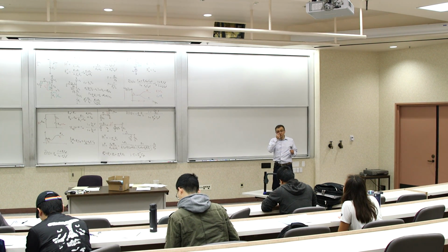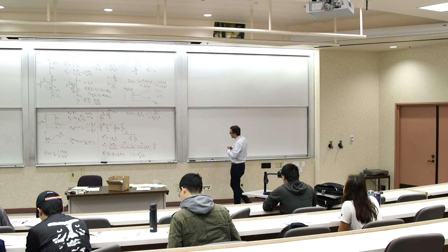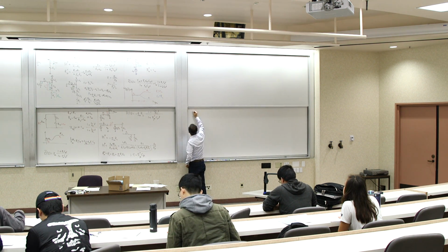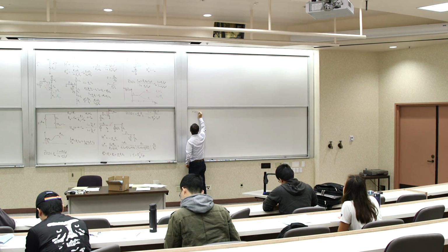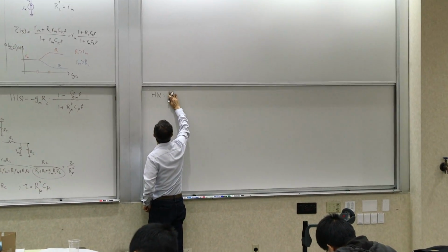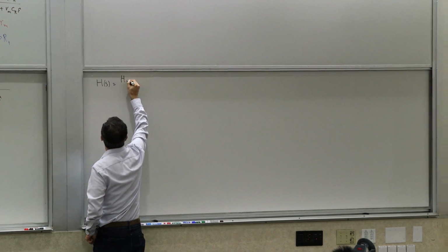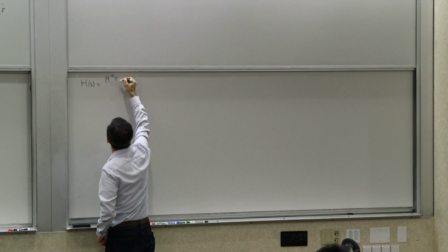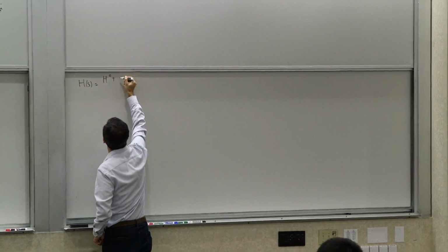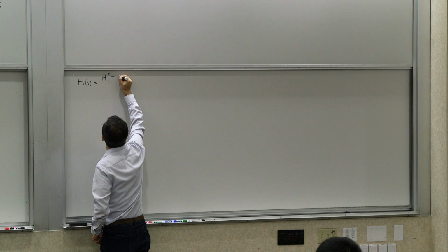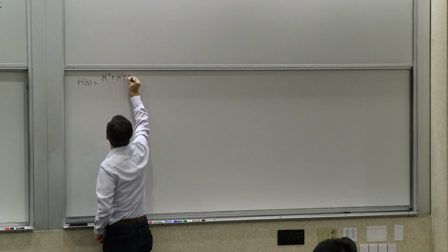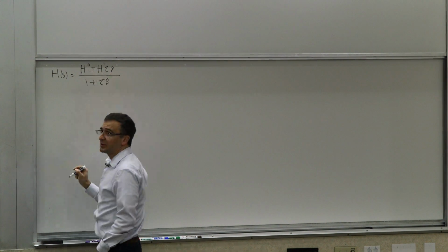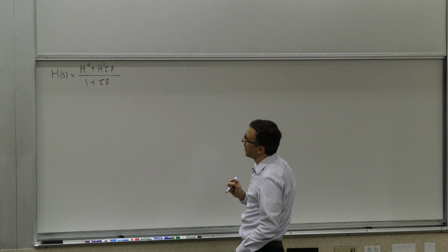All right. Before the break, we looked at some transfer functions of some systems and a couple of examples of circuits. We used this expression for the first order transfer function. We wrote the transfer function in terms of two transfer constants and a time constant for a first order system, as h0 plus h1 tau s over 1 plus tau s, where h1 and h0 were the transfer constants and tau was the time constant.